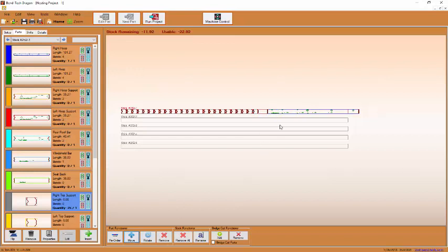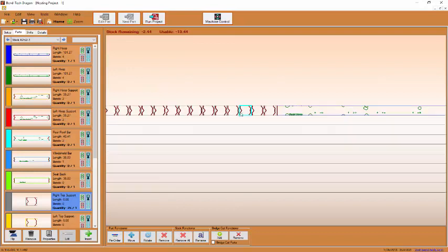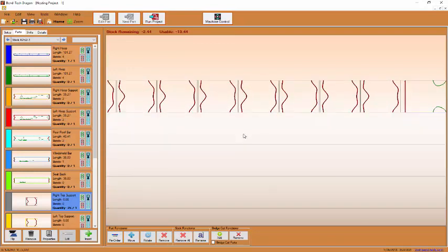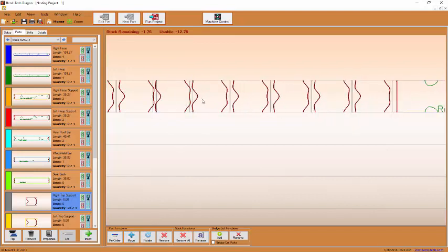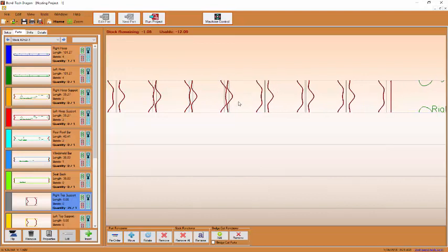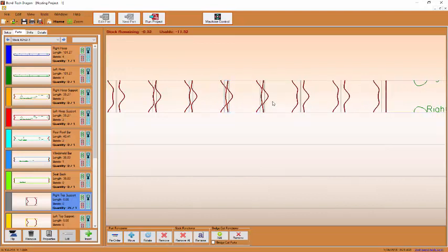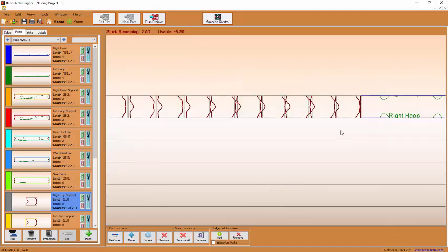Now, I'll move this so that it won't fit. Okay. Now, it will fit because you see the end cut here and the start cut here. There's quite a bit of gap, and we can close that in by using this move button and closing it in. And that's another good way to eliminate drop. Eliminate drop length almost altogether. You can always do that.